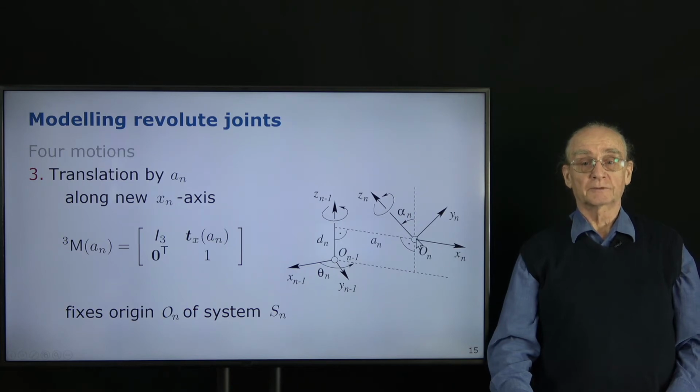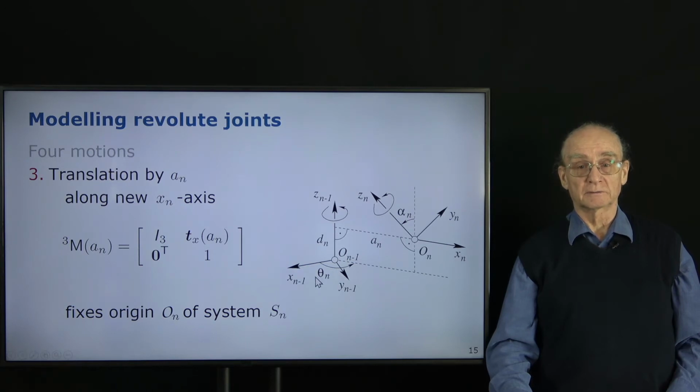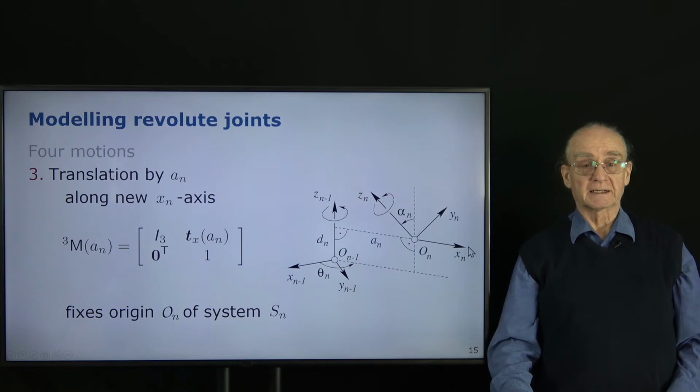Now what we have achieved is the following. We have the x-axis going here, the z-axis going upwards, and the y-axis being horizontal, parallel to the xy plane before. That means we still need a rotation of the z-axis from this direction into the actual z-axis which we want to achieve. That means we have a rotation around the x-axis.